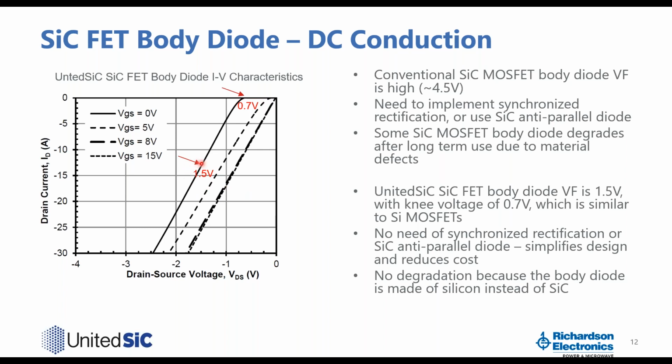And this body diode VF does not degrade at all. This is because this body diode is actually a silicon body diode instead of silicon carbide. And I will show you later on how the reverse conduction works in the following slide.